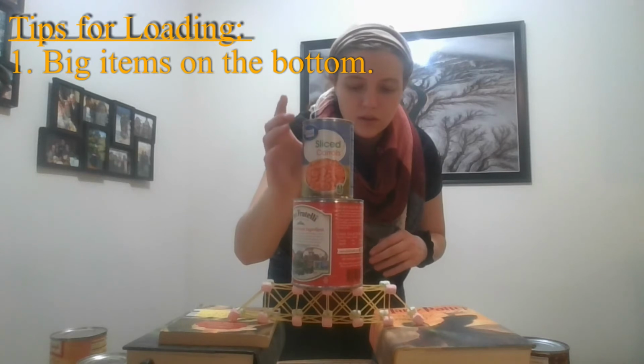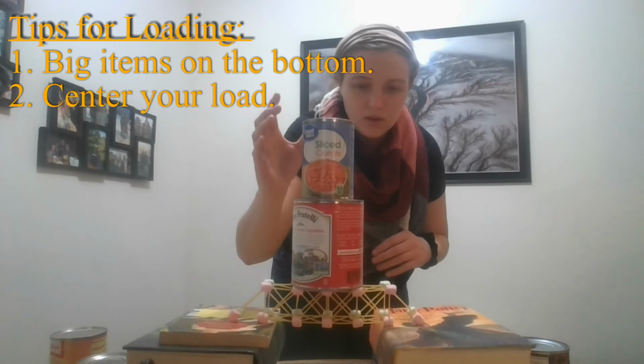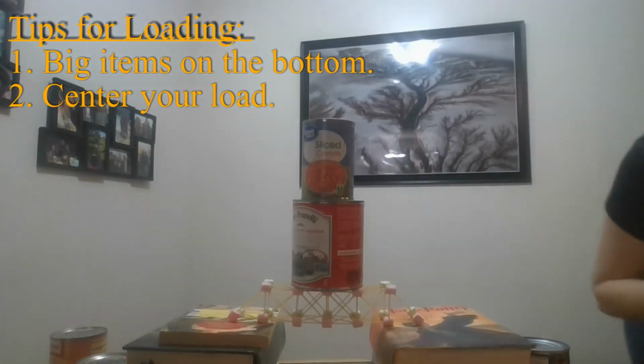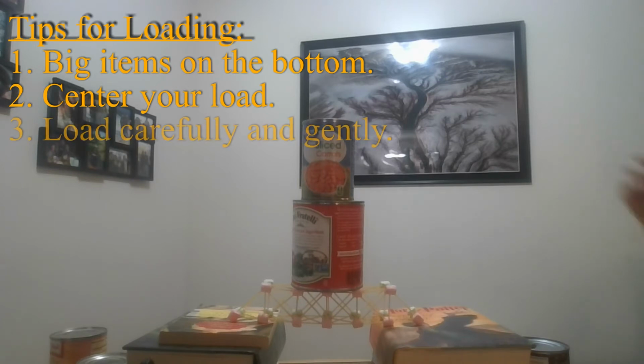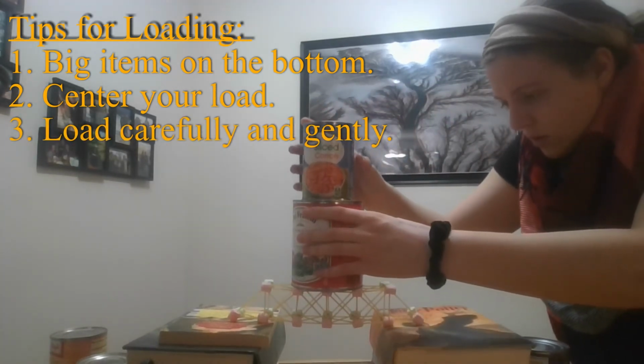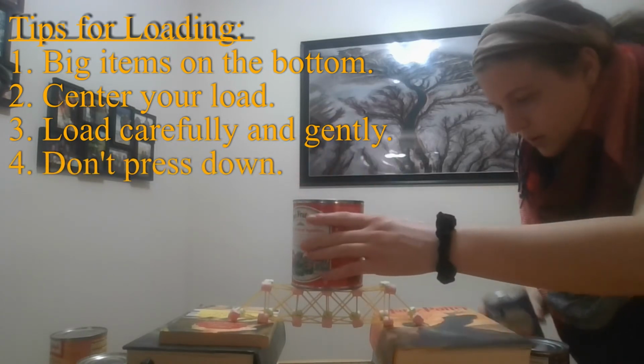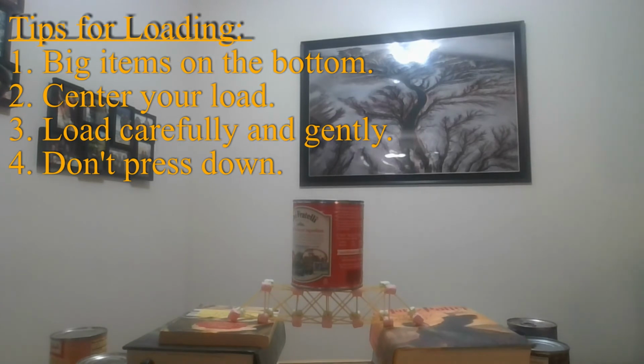Something that's very important is you don't want your bridge to twist too much, so you have to stack it as close to the center as possible. You should load everything very carefully. If you drop your material accidentally onto the bridge, you don't want that extra force to cause the bridge to break early. Another thing you want to make sure you don't do is accidentally press down on the bridge as you load.